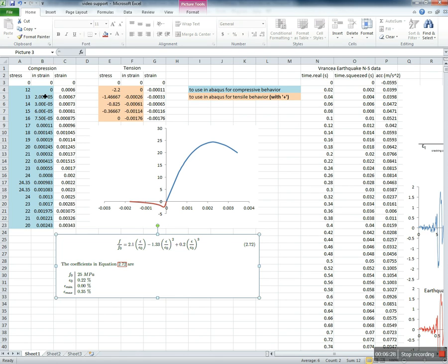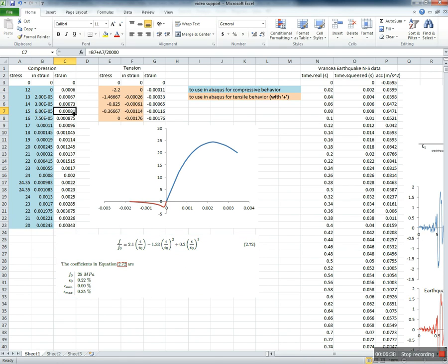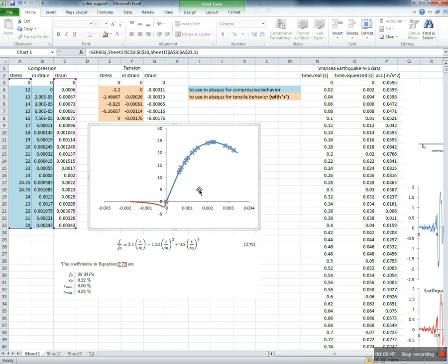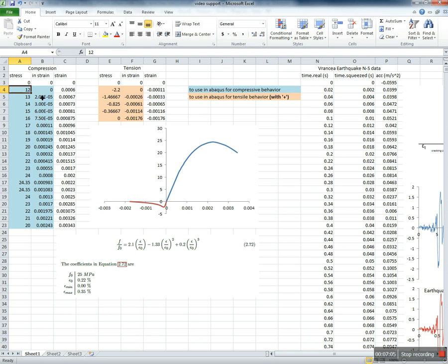So you can also define it like this, but make sure that you only define the inelastic strains in Abaqus, because you don't have to define the total strain. So if you want to do it like this, I just marked with colors what you have to put in Abaqus. So again, the curve is drawn on this graph with total strains, both for the compressive and for the tensile stress strain behavior. But in Abaqus, if you want to describe the same phenomenon, you have to use the inelastic strains or plastic strains, and the inelastic strain is the total strain minus the elastic strain, right? Okay, so these are the inelastic strains for the compressed fiber.